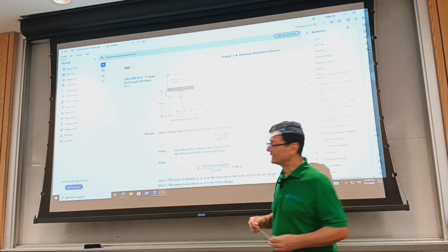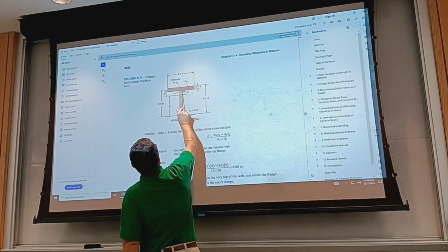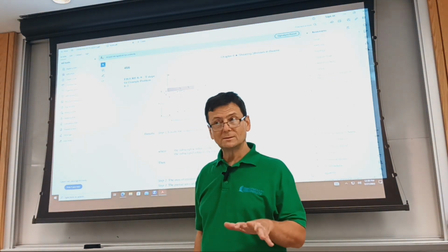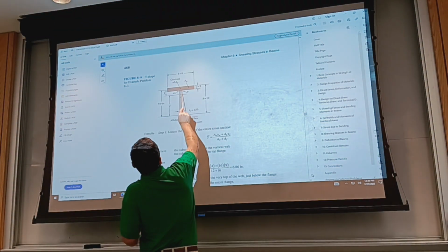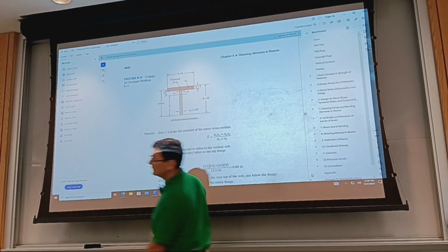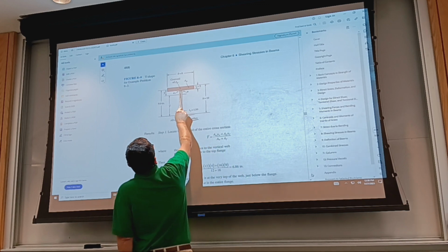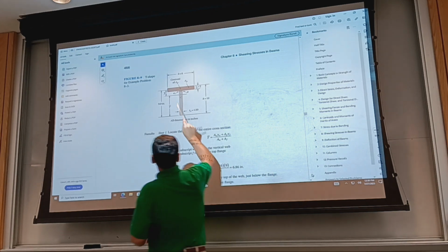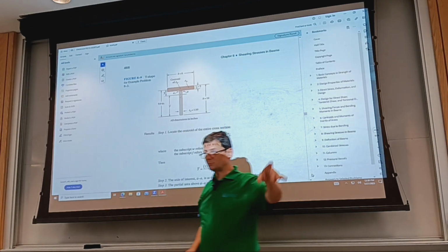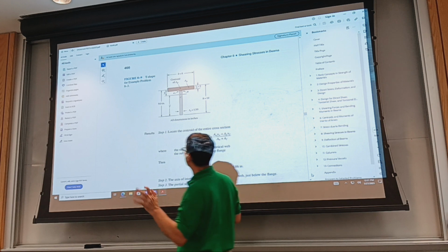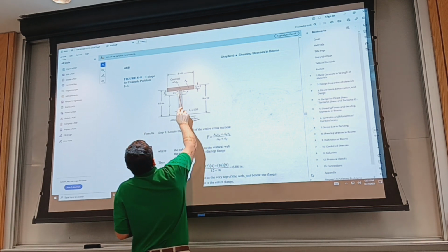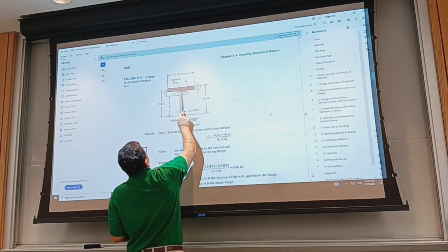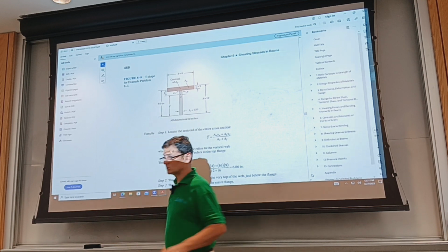That was a particular case where the area or cross section of interest was centroidal, but it's not always the case. So I may be interested in an area elsewhere than through the centroid, this one, right? Say I want to know for some reason, maybe this is where the joining happens, what the shear stress is given the V from the shearing force diagram. To calculate that first moment of area, I need to get the centroid of the full cross section.